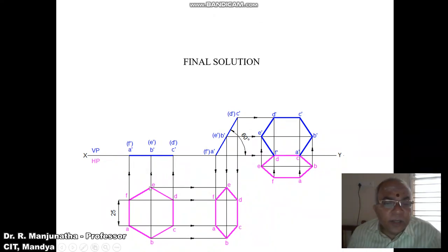So first we will draw a vertical line. By using the compass, you take a radius of 25. Consider any point on that vertical line drawn. With that as center, draw a smooth circle, which should be a light circle, such that it will cut this vertical line at this point and also at this point. You mark those 2 points as B and E as shown.